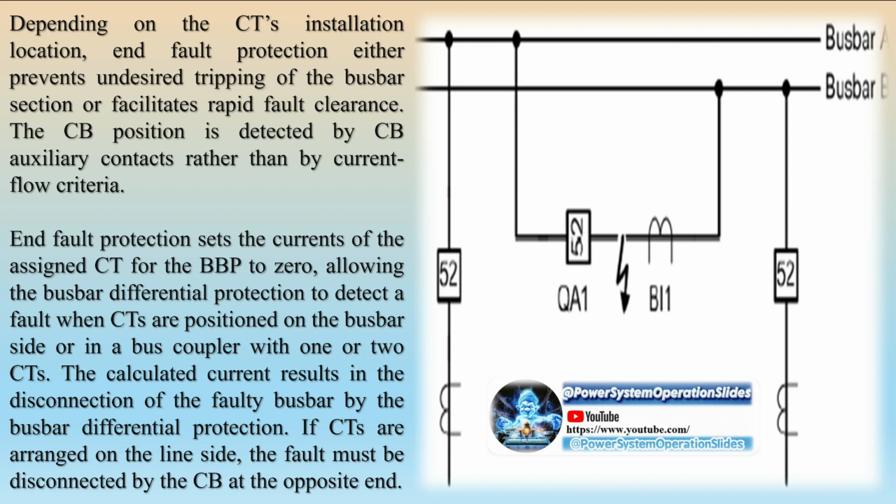Busbar splitting. Busbar differential protection is defined by its protection zones, which isolate bus segments using circuit breakers in the event of faults. The goal is to isolate only the affected busbar section after a fault. When multiple protection zones are applied, a busbar splitting strategy is implemented. The positions of the current transformers (CTs) are crucial for optimizing this strategy.